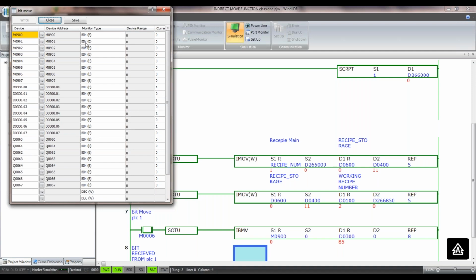So basically, from one PLC, I'm taking memory locations and moving them into a word, transmitting that word to another location, and when it gets to the other side, it's received in the other PLC or other device, and I'm taking that word and breaking it out into bits. So when I turn this on, this will be copied into these outputs right here.